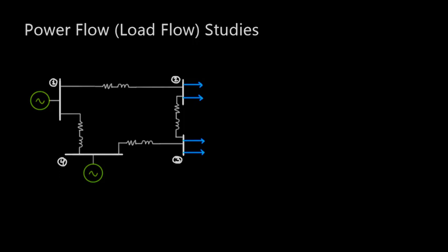And so because of that, we can run our power flow or load flow study in what's called the per phase system, meaning we just draw a single line or a one line diagram that looks like this, and then we use this diagram to perform our power flow study. Because again, we basically just draw one phase and we're assuming that the system is balanced. So if we're talking about A phase in the system, we assume that B phase is lagging by 120 degrees and C phase is leading by 120 degrees for an ABC rotation system.